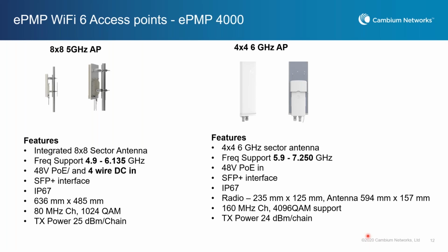If you're on a clean channel and in the higher 30s on the SNR, you will get it. But the link planner is the way to go to answer the distance question, because the main thing that we don't know is the antenna size. Obviously, if you go with a bigger antenna, you will go longer distance with the highest modulation.